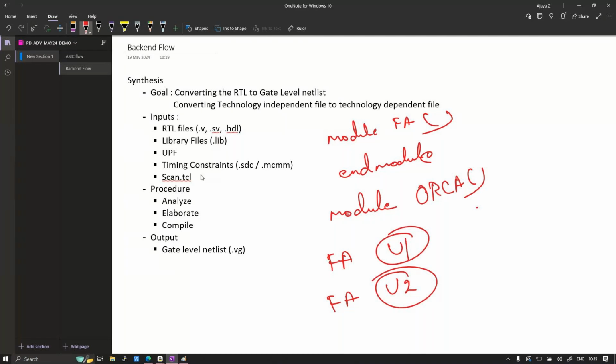So naming changes might occur from my RTL code to this gate level netlist conversion, because of optimization happening internal to the compile. We will have that naming change. That means square braces might be converted to underscores, or some of the flip-flops might be removed, or some of the flip-flops might be merged. Anything can happen internal to the compile. So for this gate level netlist, I now have naming changes, so the UPF file also has to be extracted and passed.